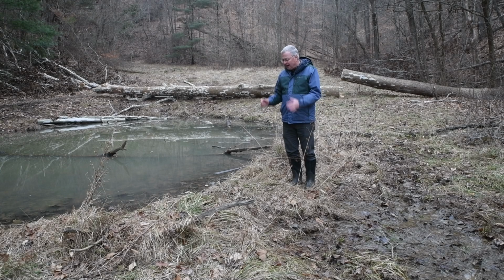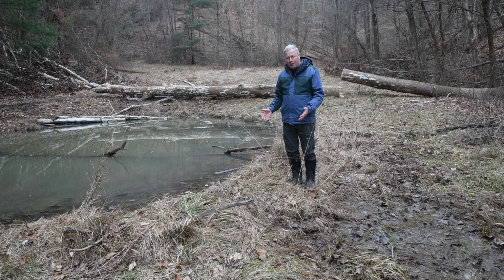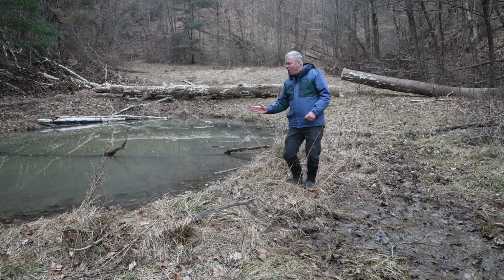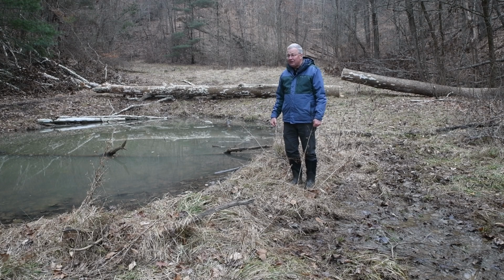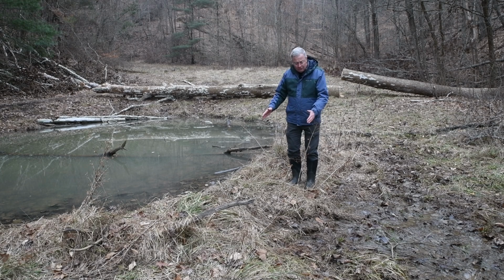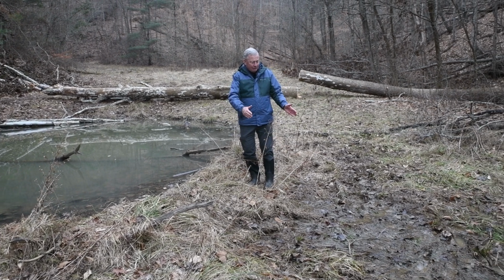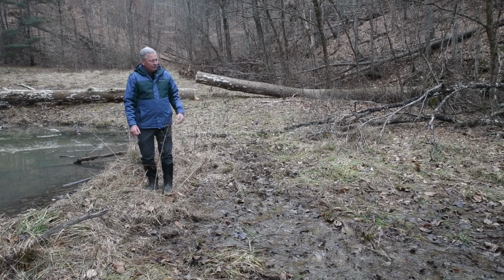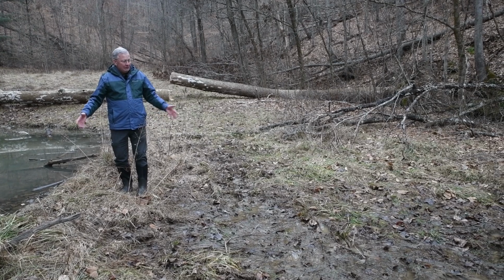I'm standing at the entrance to the spillway and I notice that the spillway is not flowing water. The reason is that somebody has blocked the entrance to the spillway by placing soil and branches, and in so doing they've redirected the water, so now it's flowing down the access trail to this wetland area. What we need to do is to remove this debris and this soil, and then get the water to spread out and to flow in a sheet pattern down this spillway so the trail is dry and the wetland is healthy again.